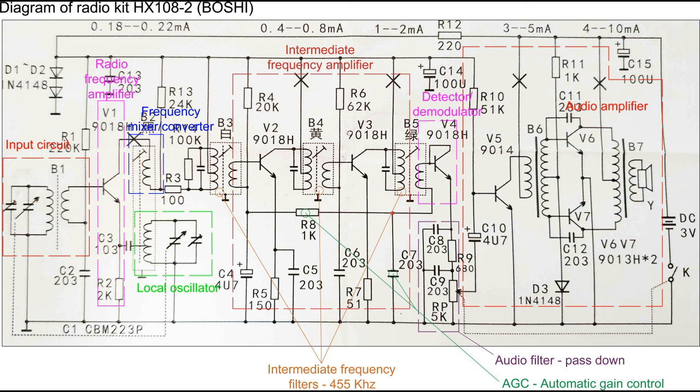Since the input signal now has a low frequency, its amplification can be done efficiently, using low-frequency amplifiers. Obtaining this frequency is done by fine-tuning the input circuit and the local oscillator. At the output of the mixer there are LC filters tuned to the frequency of 455 kHz and several stages of amplification. Tuning to the radio station is done by pressing a single button.